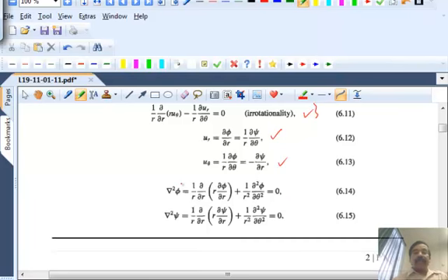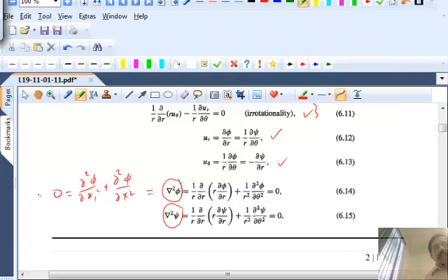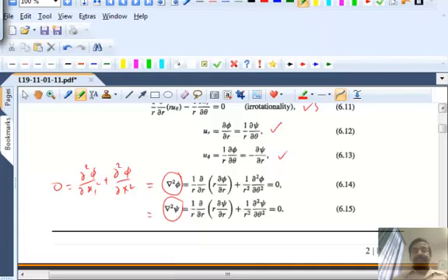And so we have del square phi equal to 0, del square psi equal to 0. What is the expansion for del square in cylindrical coordinates? Well, here it is, 1 over r d dr of r d phi dr plus 1 over r square d square phi d theta square. Okay, in Cartesian frame, this would be simply d square phi dx1 square plus d square phi dx2 square equal to 0. And similarly for psi, d square psi dx1 square plus d square psi dx2 square will be equal to 0. You should be able to work in either one of those coordinates.